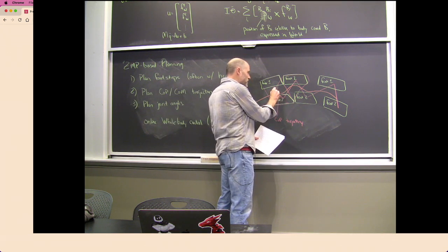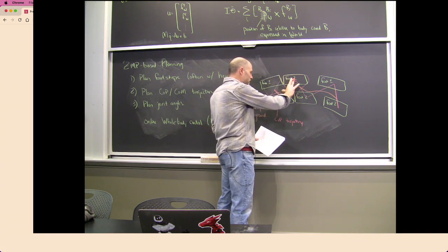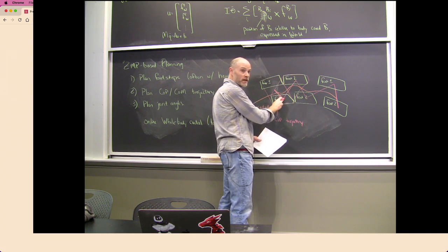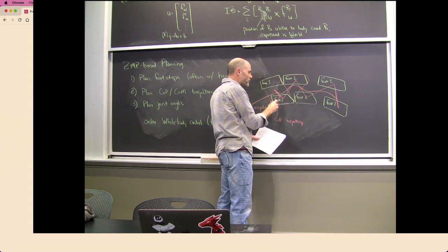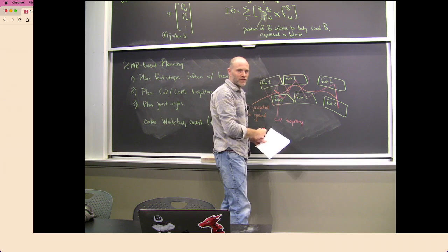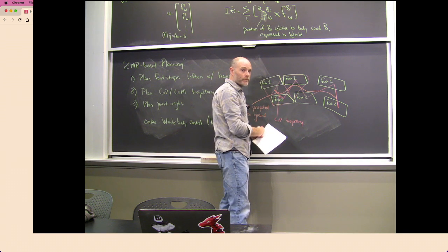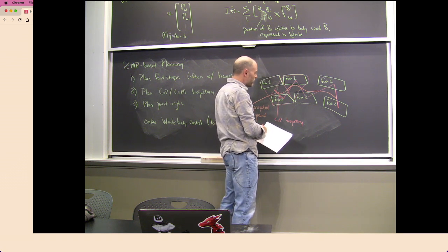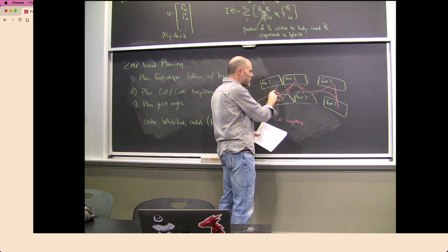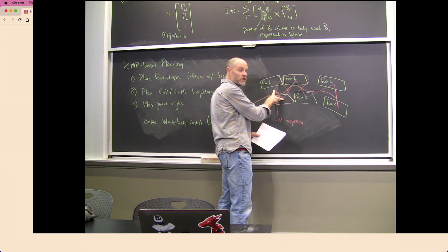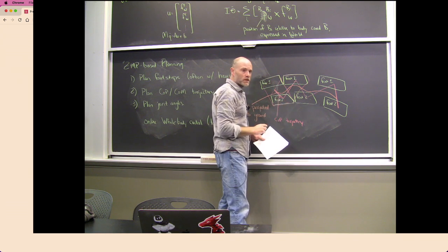You're absolutely right that you have to be careful about the timing of your foot picking up. You wait to pick up your foot until you're inside here. Since I've got my foot sequence ahead of time, it's really not that hard to write that procedurally. You optimize this, and then you make sure that the foot lifts happen while the center of pressure is somewhere allowable. I think we've done both. These are linear segments, and you just make sure that you're inside your foot by the time this foot comes up. I agree with you.